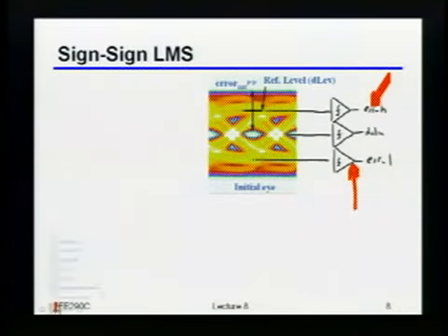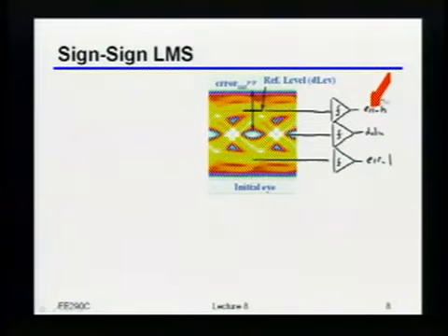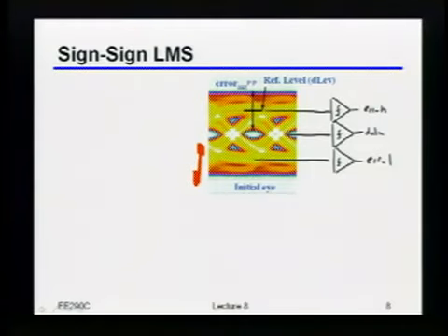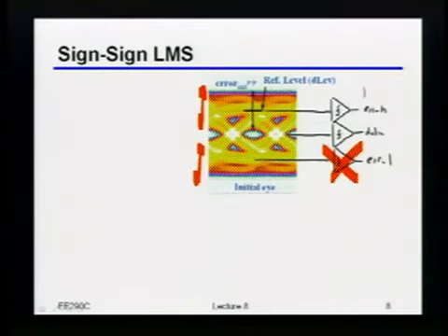So basically, what you will indeed occasionally do is you'll just say, well, you know what? As long as everything is reasonably linear, there's no really extra information in the errors around here versus the errors around here, right? So what I can basically do is just throw out one of those comparators and then only do updates when I actually have valid error signals coming out of that upper comparator.